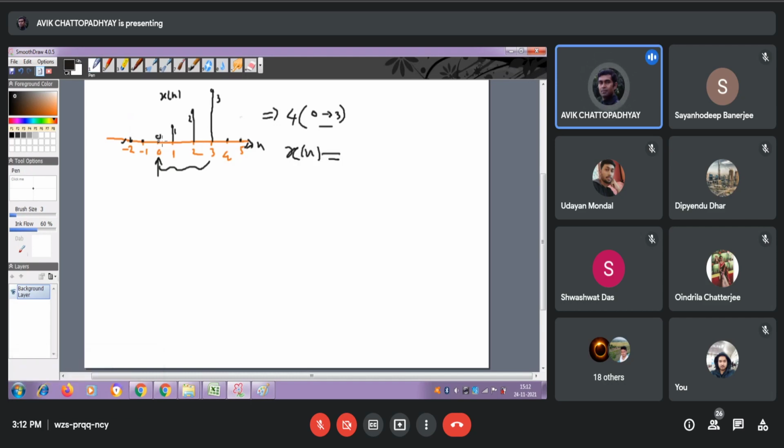The first delta function gives you 0 value. Delta is 0, so there is no need to write it. Please note that though I am telling the length of the signal is 4, still while representing the signal, I am not writing delta[n], because that would mean at n equals 0 you have a delta whose amplitude is 1, which is not true. So the first thing I have to write is delta[n-1], a one sample shifted version of delta[n].